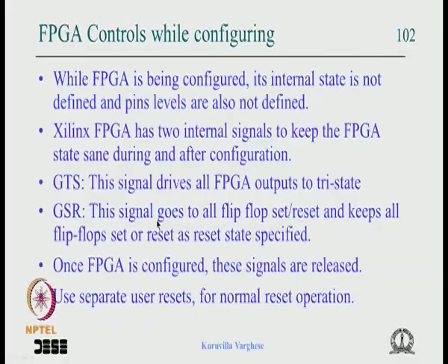and once the FPGA is configured, all the flip flops are reset using an internal reset line, which the FPGA doesn't advise you to use as a reset. So in your circuit, even for the power on reset, you should implement a separate power on reset rather than this internal reset signal, though there is a way of using that reset signal within your design. A lot of flip flops are connected to it, so it's very heavily loaded, and it may be a better idea to reset separately, which gives a good drive.